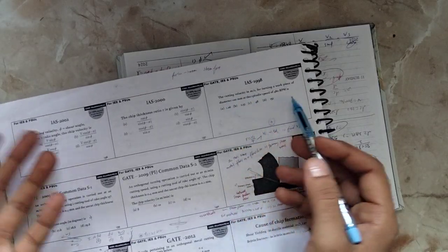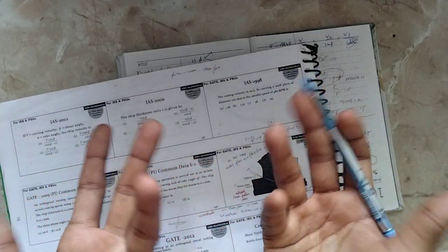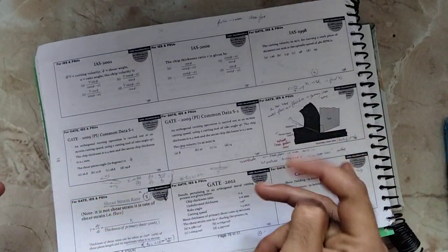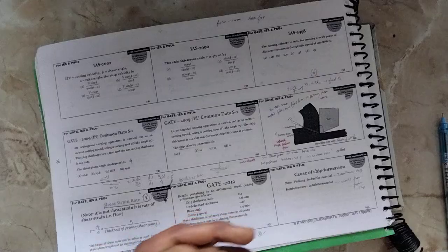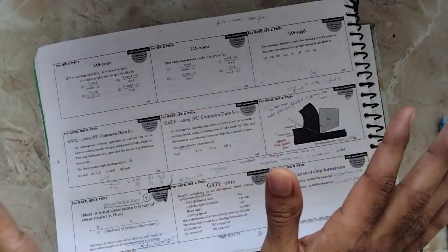So we go to pi dn. This is revolution per minute, but we need revolution per second, so that gives meter per second. Convert by dividing, basically, that's it. Okay, I think you can understand. So guys, it's not a bigger thing and it's also not a small thing, just take it casual.